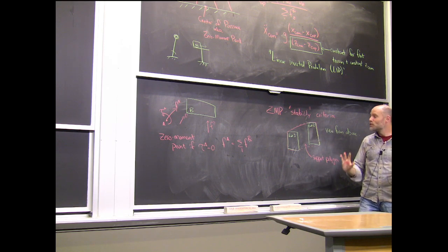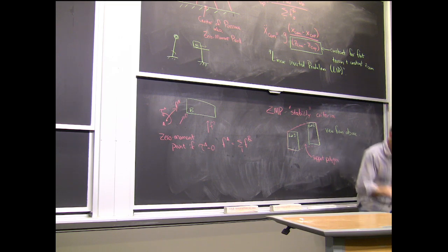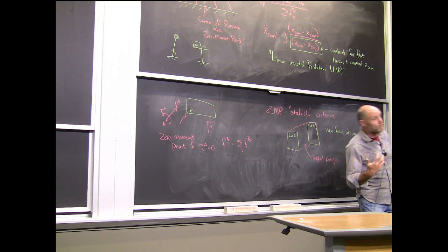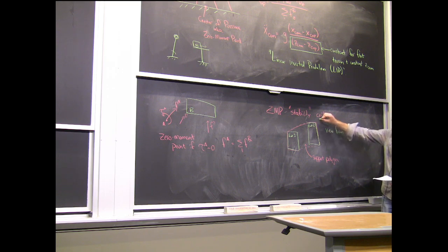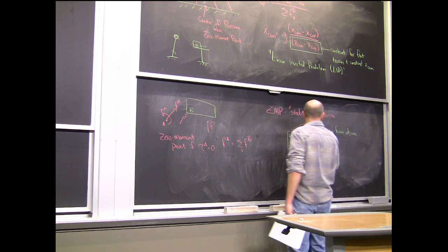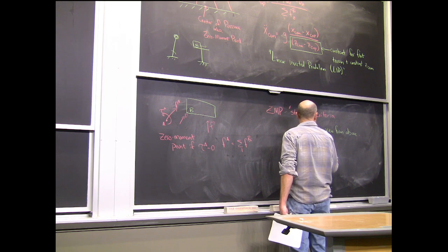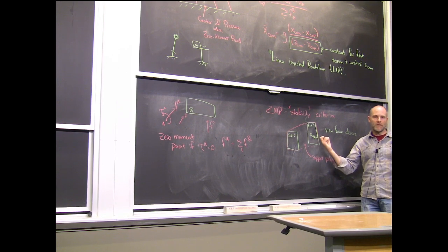That's been used in the past as saying you cannot be falling down. Okay? I mean, you could still fall down directly into the ground, but people say you cannot fall down if your center of pressure is inside your support polygon. What they really mean is you can't tip over the side. Okay, so one of the things that people do as a stability heuristic, I would say, really, is they say that the distance of your center of pressure to the closest point of the support polygon, you can use that as a measure of how stable you are.